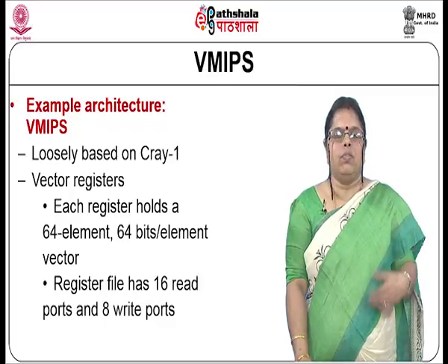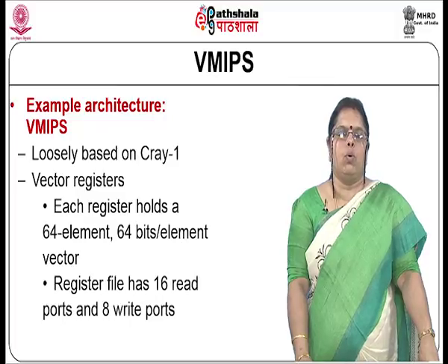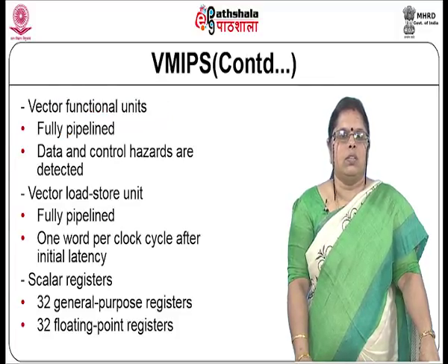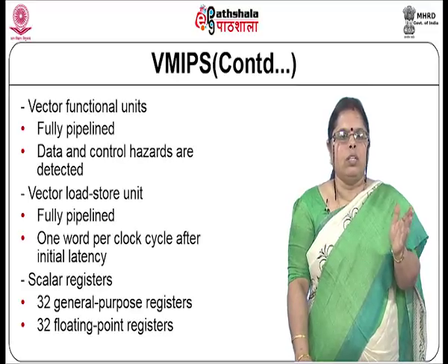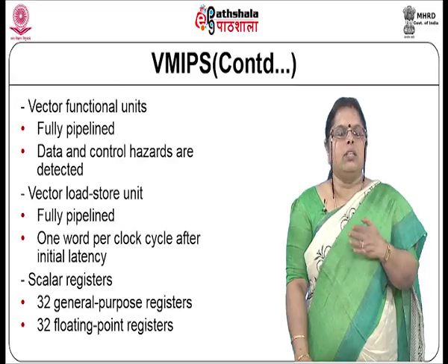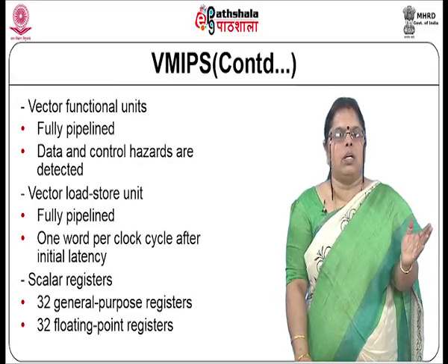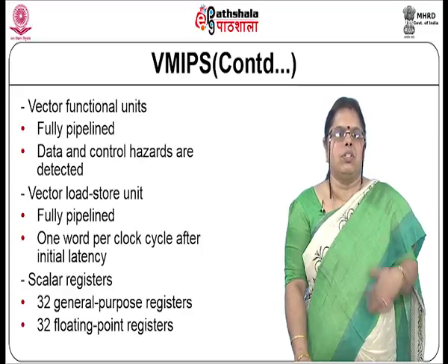Such is the size of the vector registers. And you also have more read and write ports supported to the register file. As far as the vector functional units are concerned, they are fully pipelined. So, once the first element enters the functional unit, as it moves down the pipeline, the next element is given to it. So, every element moves through the entire pipeline and finishes the operation.